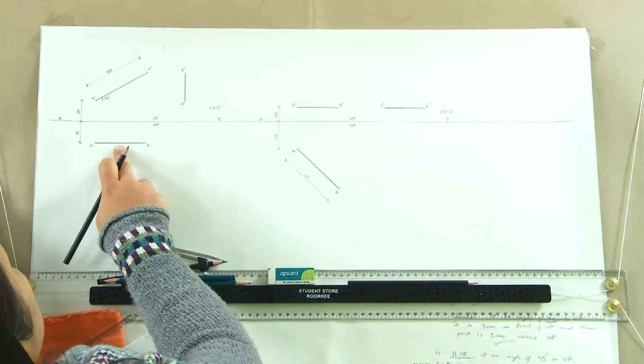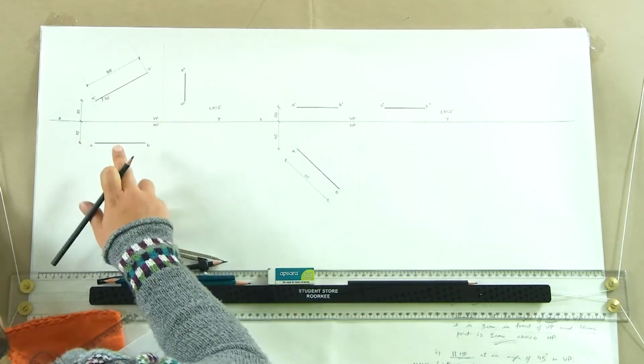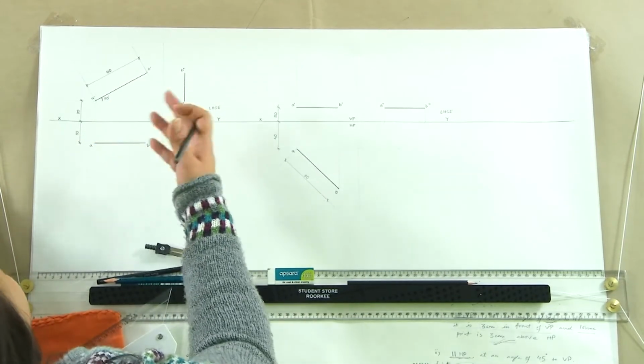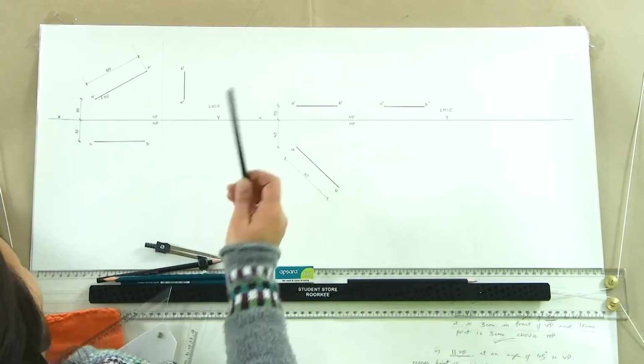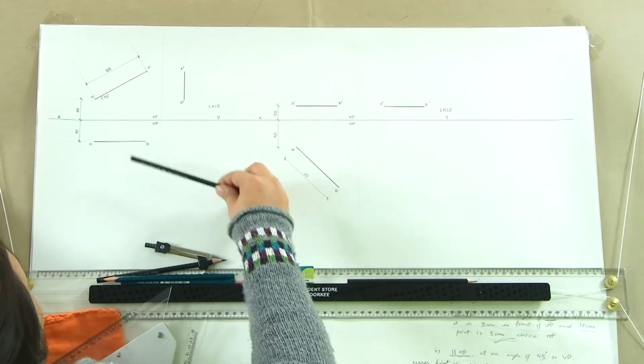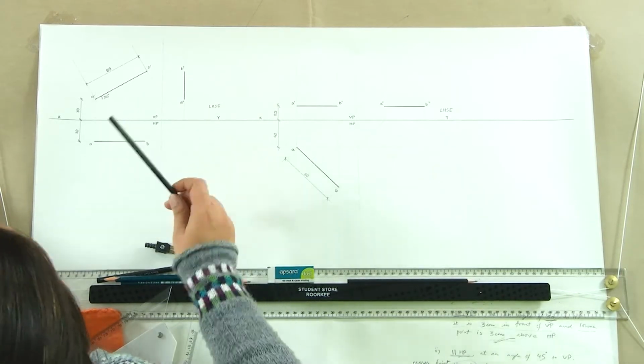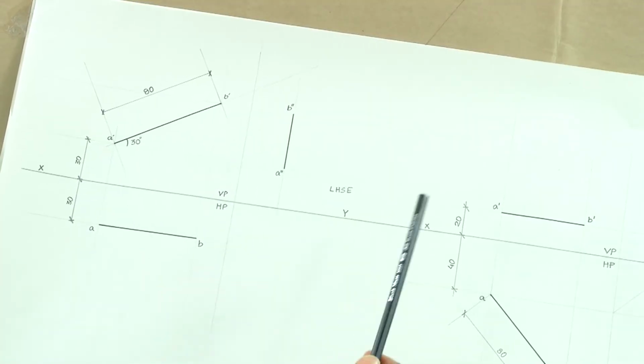Always the darkest lines will be the ones which are in the actual object, projections of the actual object. The next ones come the reference line, then the dimension lines, and the last and the thinnest of them all are these projection lines, which are just the guidelines and nothing else. And in case you are drawing guidelines for writing the text, then those guidelines are also as thin as projection lines or even thinner than them. They should not be seen, they are just to guide us.